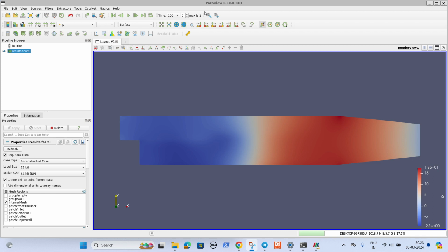Hello, in this video I'll discuss how to use Paraview for exporting data to be used in data analysis and machine learning. Here you can see a case file from an OpenFOAM simulation, and this is the simulation for the pitzDaily case. Here I will export data for the entire computational domain, that is x, y and z coordinates, and also the velocity, pressure, turbulence kinetic energy, turbulence dissipation rate and turbulent viscosity.